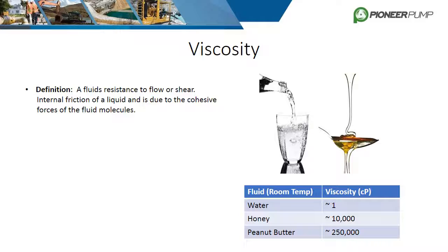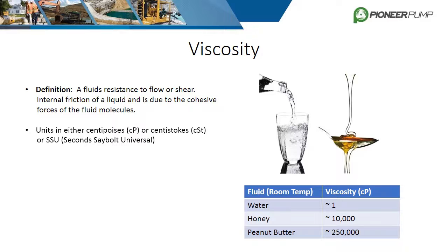The definition of viscosity is a fluid's resistance to flow or shear. It is the internal friction of a liquid and is due to the cohesive forces of the fluid molecules. The units for viscosity are usually one of the following: centipoise, centistokes, or SSU. In most cases, the viscosity is related to temperature, meaning that as the liquid warms up, its viscosity decreases and